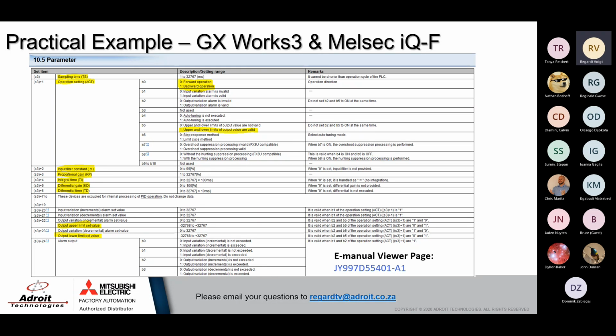I can say the following: the two biggest causes for overshooting will be, first, your P gain is too high. In other words, your KP value or your K value, depending on the controller you use. So you need to reduce that. Another reason would be your KD value can be too high. If your tank level is too small, let's say a small tank with an oversized pump, or a large pipeline with a large valve in there, then your KD is too large. So you have to reduce your KD value.